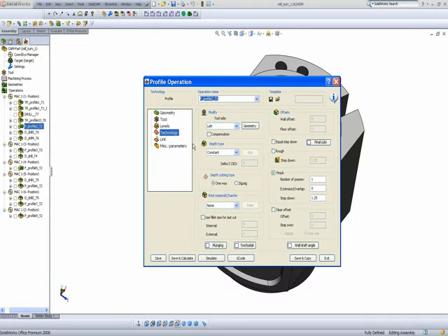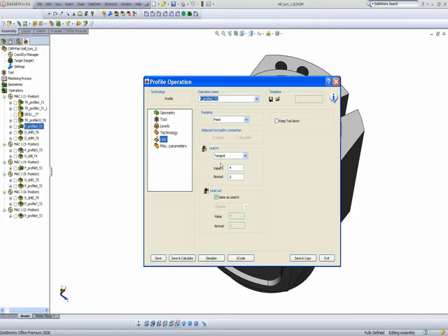And my technology, as you can see, this is a regular milling operation. All the functions that we have in normal milling, we have it here also. Working one way, constant, doing a finish cut only in this particular case, at a step down at 1.25 millimeters. Of course, we have our lead in and lead out, both being used as a tangent of 4 millimeters.